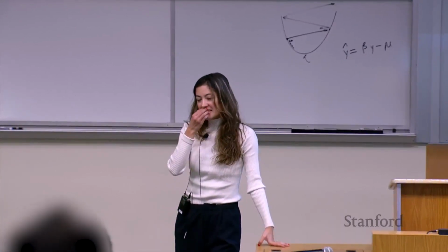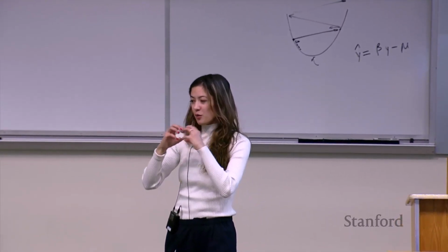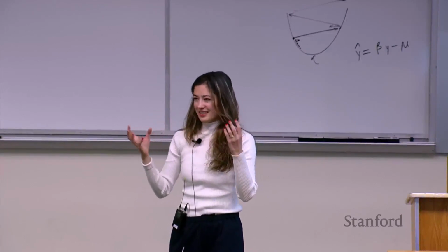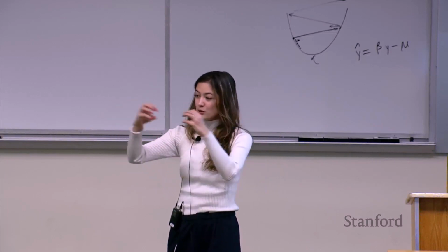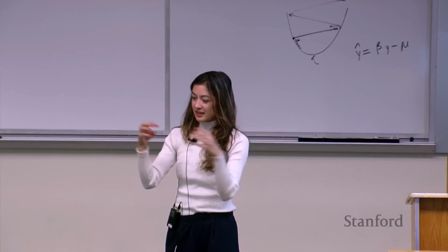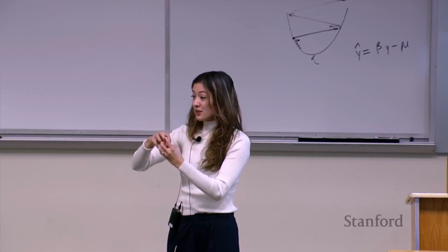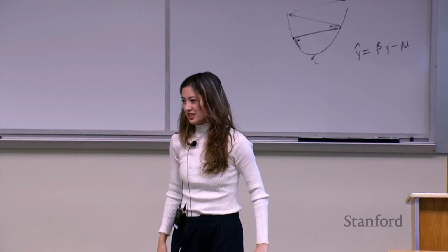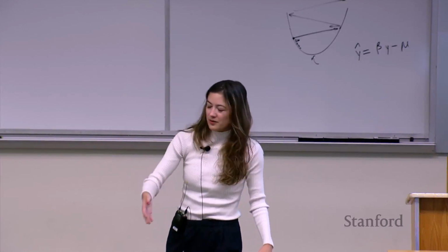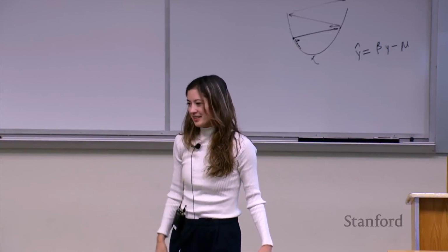Yeah, that's a really good question, because that was actually one part that we did incorporate into our model, which is looking at the number of points of connectivity from one block to another. We had a block, and we could have different degrees of rotation. It's hard to visualize without the visual. But basically, when you have 2 blocks together, you might have one that only has a few points of connection, and that's not a very strong connection. Whereas if you put a 90-degree rotation to connect them, it's very strong. So if you look at the total number of points of connection of each individual block, you can use it as a proxy to see if it's a very rigid structure or one that's not. And we also just threw out ones that we thought just didn't have enough points of connection. It's not going to be structurally stable enough.